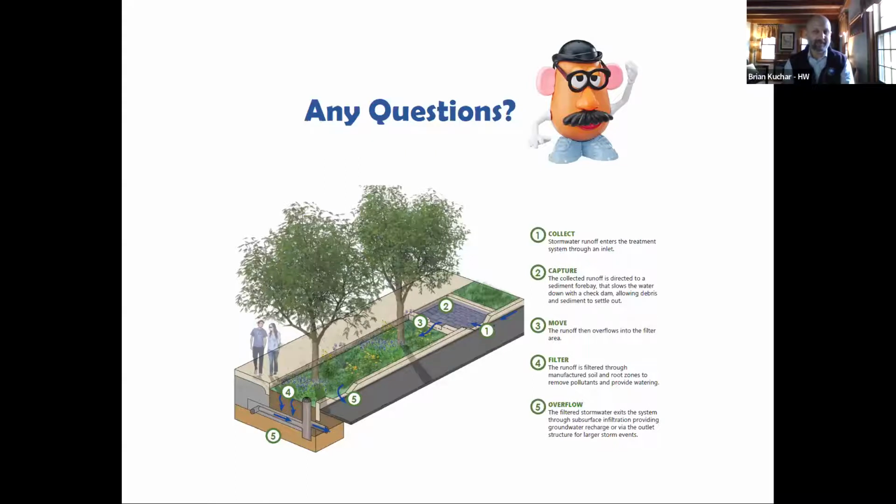Ellen or Brian? Yeah, I would add that, in the Stormwater Center, we've had lots of discussions with researchers and engineers about trees actually in these stormwater elements or just outside. And do trees installed just outside, or as you suggest, an existing tree where you build this next to it, provide the contaminant removal that we're looking for if it's not actually in the practice? So some of the problems with it being in the practice are the media is typically a sandy media so that you'll allow the water to flow through at a quick pace. Well, sometimes it flows through too quickly so that the roots of the trees can't draw it up.